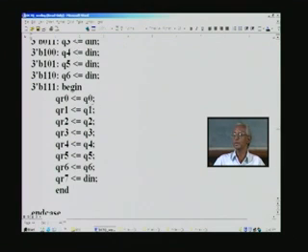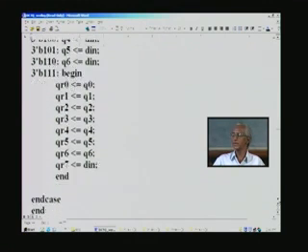That is possible if you write at this stage into another register called QR0. So, with the write at the 8th clock cycle, we transfer all this Q0 through Q6 content into a safe register here, and as well transfer the last thing which we have not done before into this. Now, with the arrival of the next clock, this Q0 will be overwritten, but not QR0. The QR0 will be overwritten only after all the 8 clock cycles. So, thus if you examine this, this will be available for the next stage computation to the tune of 8 clock cycles, and this completes that DCT register.